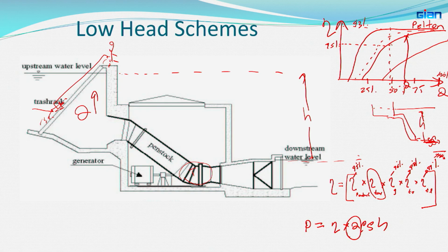We do not have to do it for transformers and generators, etc., for penstock, etc., because from no load to full load, the difference may be 1%, right, not very significant. But for turbines, it is pretty significant. Therefore, we have to use the correct efficiency corresponding to the operating point.